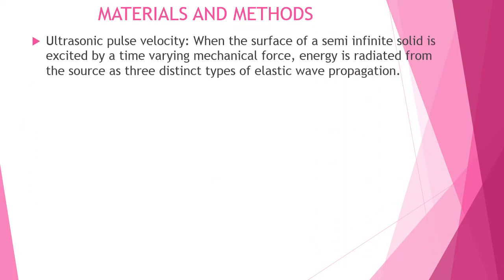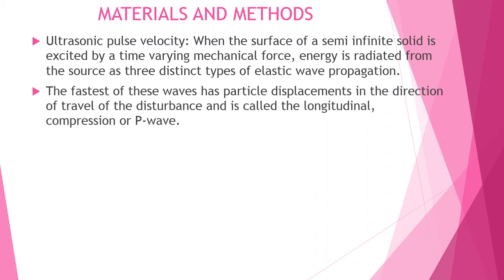Materials and methods. Ultrasonic pulse velocity. When the surface of a semi-infinite solid is excited by a time-varying mechanical force, energy is radiated from the source as distinct types of elastic wave propagation. The fastest of these waves has particle displacement in the direction of the travel of the disturbance and is called the longitudinal compression or P wave.